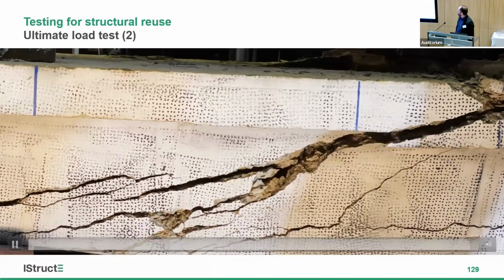And then what you can see here as well, there is a longitudinal crack, which was a post-debonding, I would say, because when the slab was cut, there was no additional anchorage, nothing else. So the only bond was between the rebar and the concrete itself.